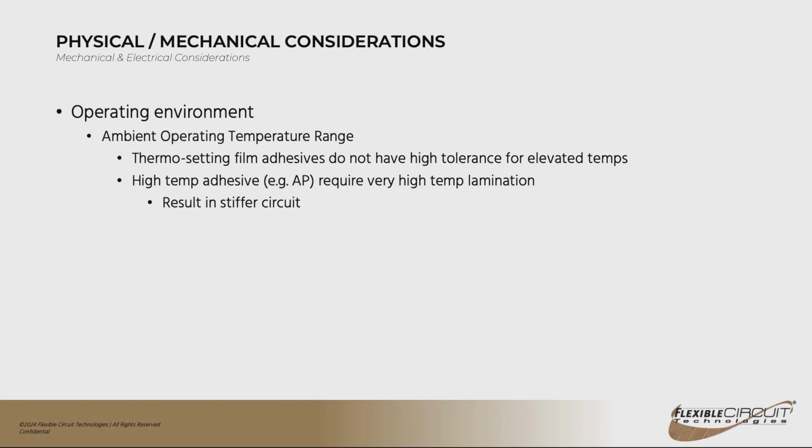This is going to have a definite impact on the stiffness of the circuit because these adhesives are stiffer, and it's also going to have an impact on the overall cost and on your supplier base, because not every supplier has equipment that can laminate those high temp adhesives. If you have physical space limitations, this is pretty much going to force you to have tight bend radiuses and decrease your circuit size and thickness in order to be able to get it into the small area.